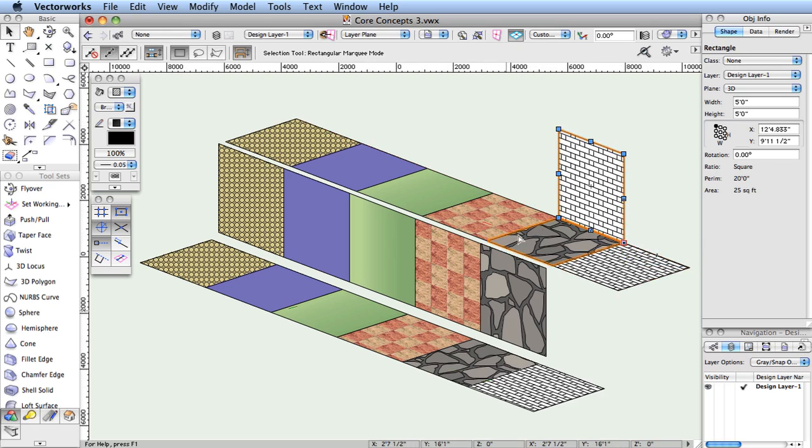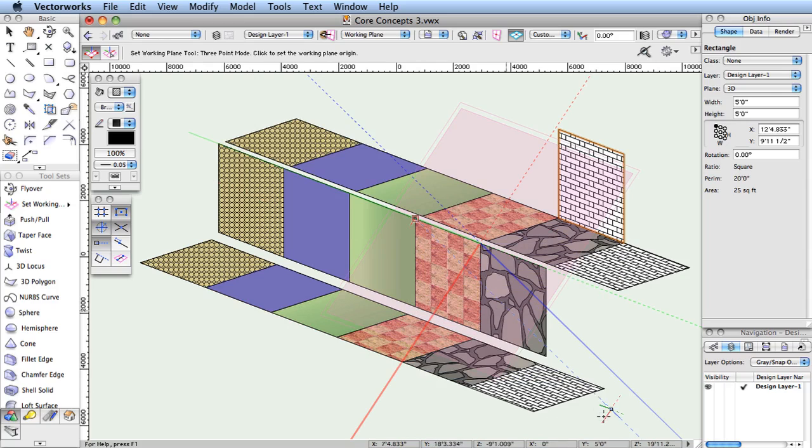Otherwise, Vectorworks requires a plane in space so that clicking the flat display can be calculated to intersect somewhere before infinity. Therefore, all object creation, editing, and moving is aligned to a working plane. A working plane is an elevation of any height on a plane of 3 points at any orientation defined by the user. Often, the user will define a working plane to make aligning and positioning tasks easier and more accurate.